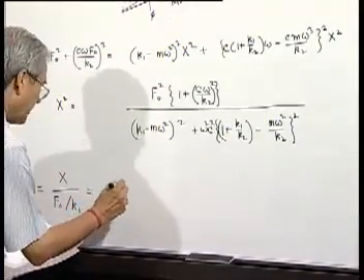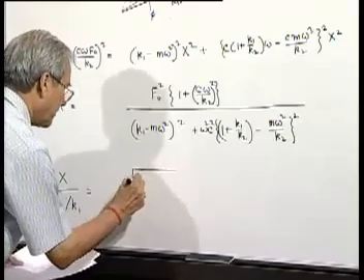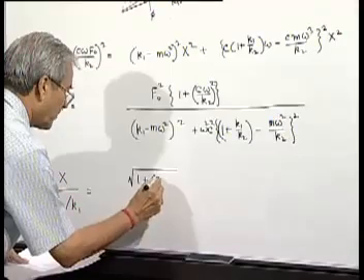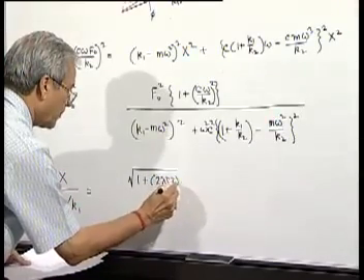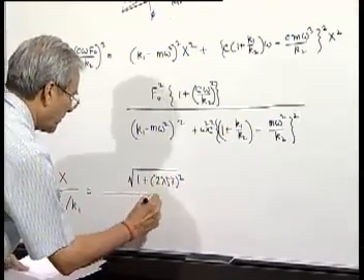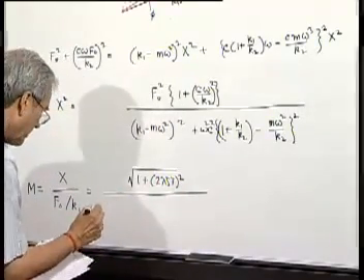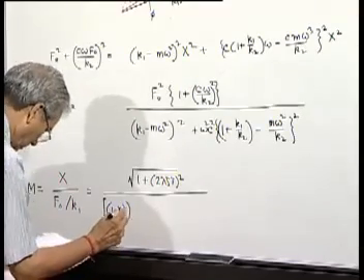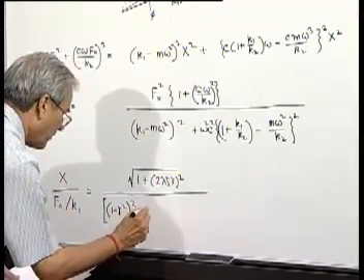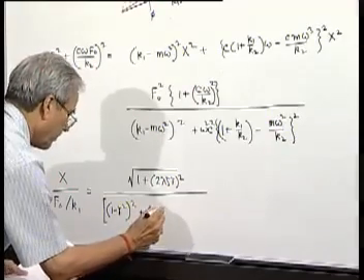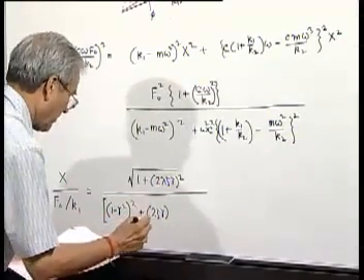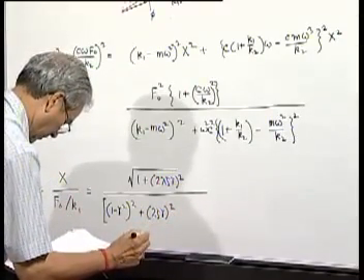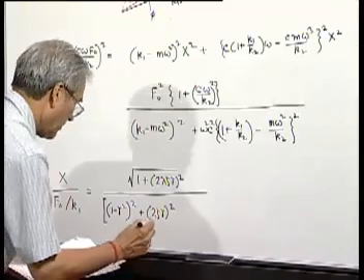So magnification factor, that is x by f0 by k1. In this case, if we apply some load statically, its deflection will be guided only by k1 spring. We can easily see that, because whatever this in the steady state or zero velocity situation, this will not transmit any force. So the only resistance to deformation will be k1. So f0 by k1 is the static deflection, and that is given by